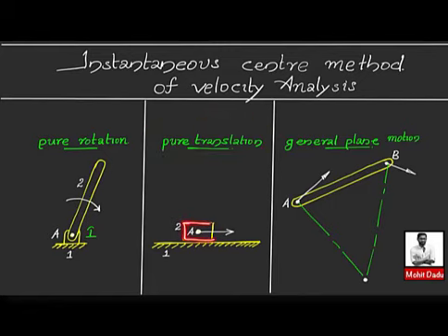Here, block 2 has a relative motion which is translation with respect to the fixed link 1. So the path is always straight. In the first case there is rotation about a point, while here you have a linear path, and you know that a linear path is equivalent to a circular motion with infinite radius of curvature.